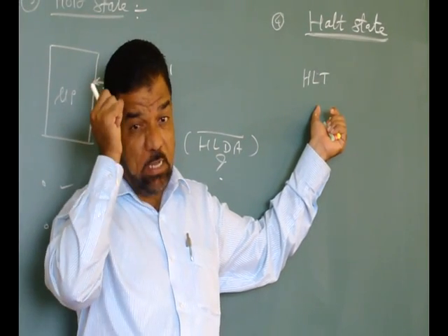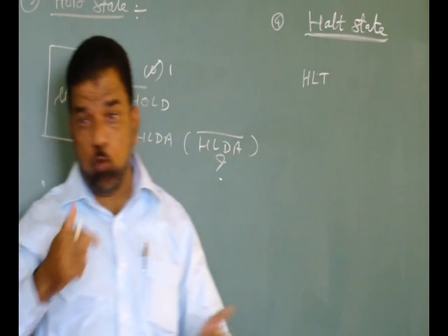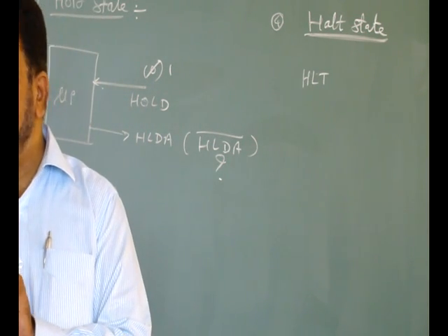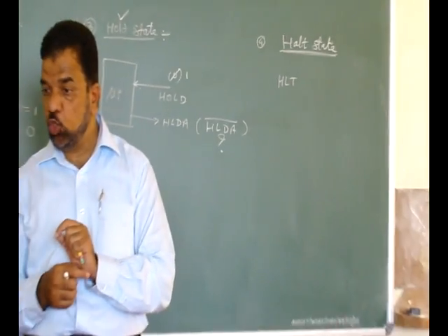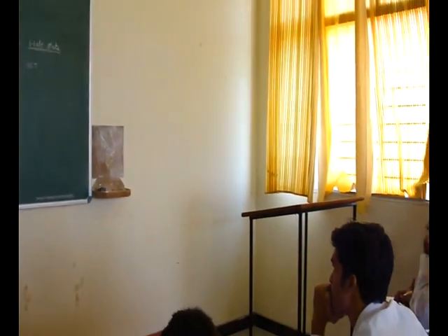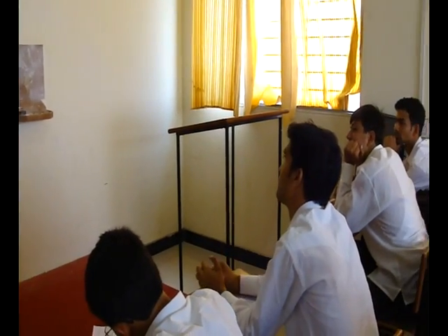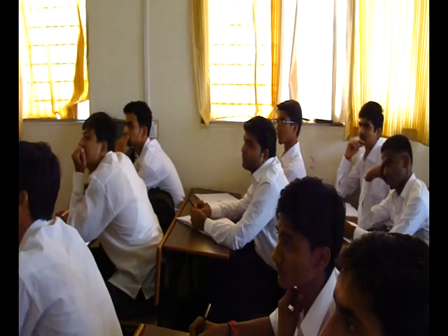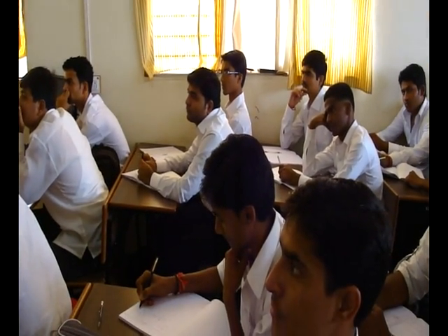Now during T3 and T4, that opcode gets decoded, and the decoder's output decides what the actual instruction is, and the instruction is to stop the processing. So corresponding to T1 of the next machine cycle, there is an internal flip-flop which we have to call the halt flip-flop.